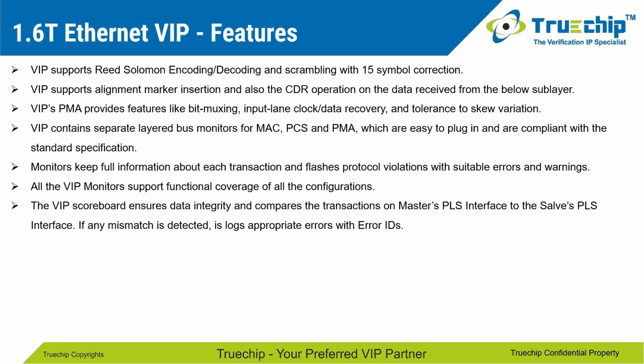VIP contains separate layered bus monitors for MAC, PCS, and PMA for easy plug-in capability and compliant with the standard specification. The monitors keep full information about each transaction and flag appropriate errors and warnings on protocol violations. All the VIP monitors support functional coverage for all the configurations.